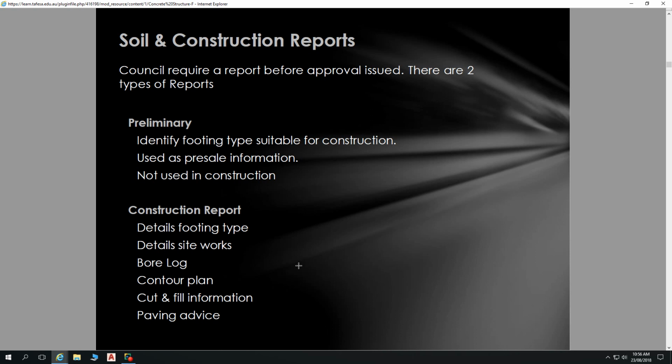They are really good at getting moisture out of soil. They'll get the moisture out of the soil, it goes up through the leaves and goes out. That can be problematic for our buildings because in wintertime we can have plenty of moisture in that soil, but in summertime the trees are just pulling all that moisture out, exacerbating that movement. There are ways of managing that movement.